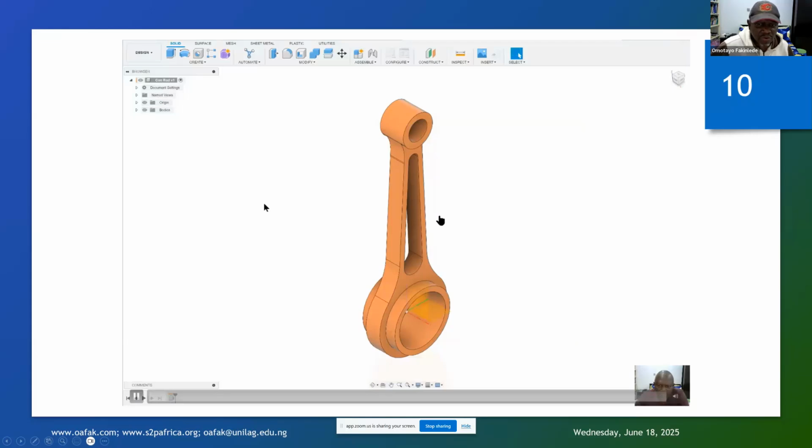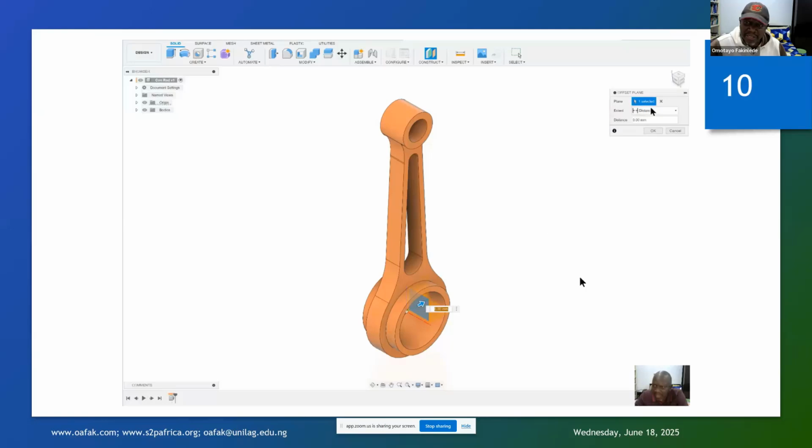The first thing you do is turn on the origin, and you go to pick a construction plane. You are going to pick an offset plane, which is an offset of the ZX plane. You take an offset of the ZX plane at a distance of 30 units on the y-axis, and that is one plane. Then you take another offset plane backwards to minus 30 on the y-axis. So you have two offset planes, and you are going to use those as splitting tools.